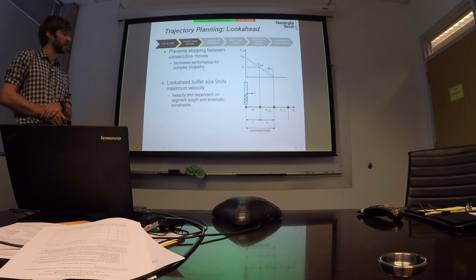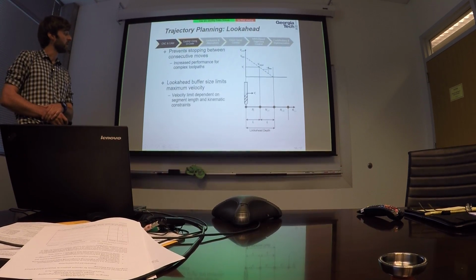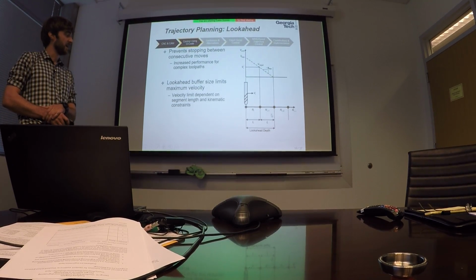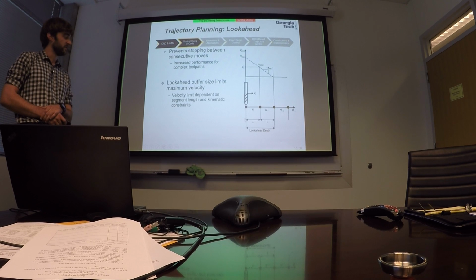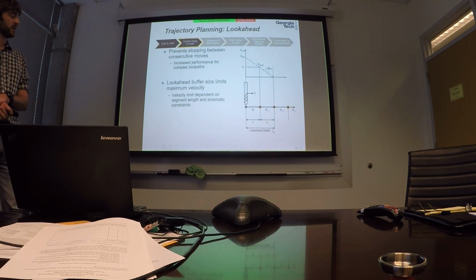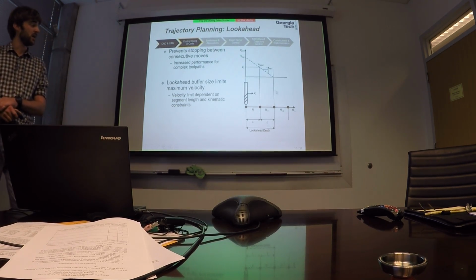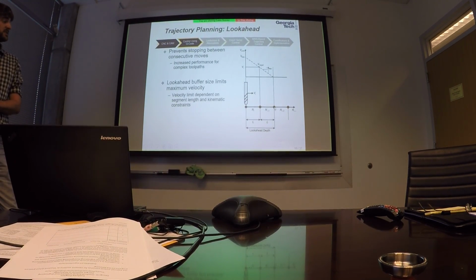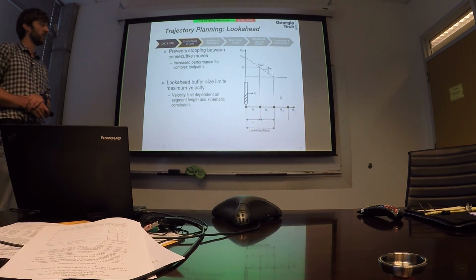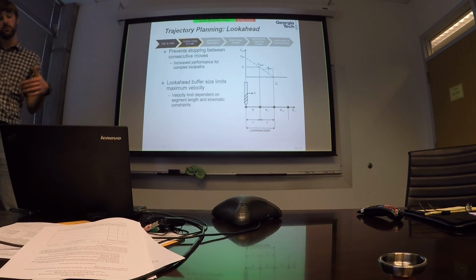So in this example, we have 2 segments of look-ahead. We are currently at this position here, traveling along block N_i. The next block is block N_i plus 1, and for the sake of this, let's assume that both blocks are of length L. So here's the look-ahead depth. We can see until the end of this block, and the machine actually has to assume the worst-case scenario that this block is the end of the program, because otherwise it may overshoot.